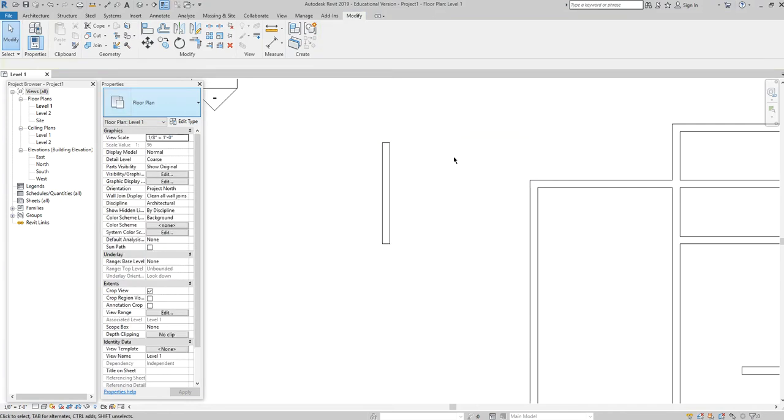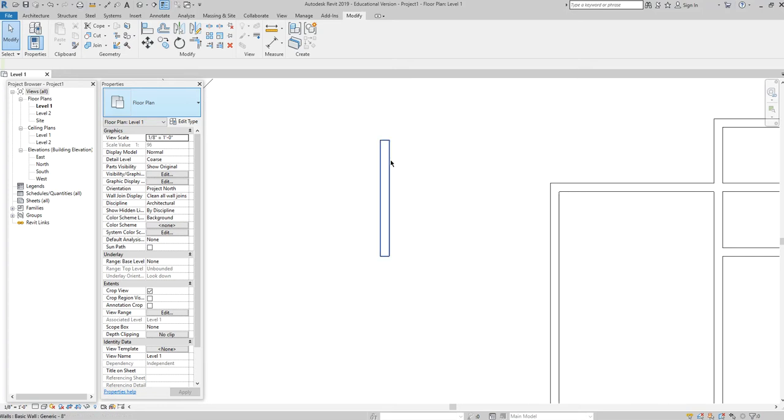Revit is really great at constraining things. I think it's one of its strengths. And this is another constraint, right? Pinning something constrains it to where it's at. It constrains its location, its length, its properties. When I first started using Revit, I thought, this program is great. I can pin things down, I can lock them, I can restrain them, more so than AutoCAD, right?